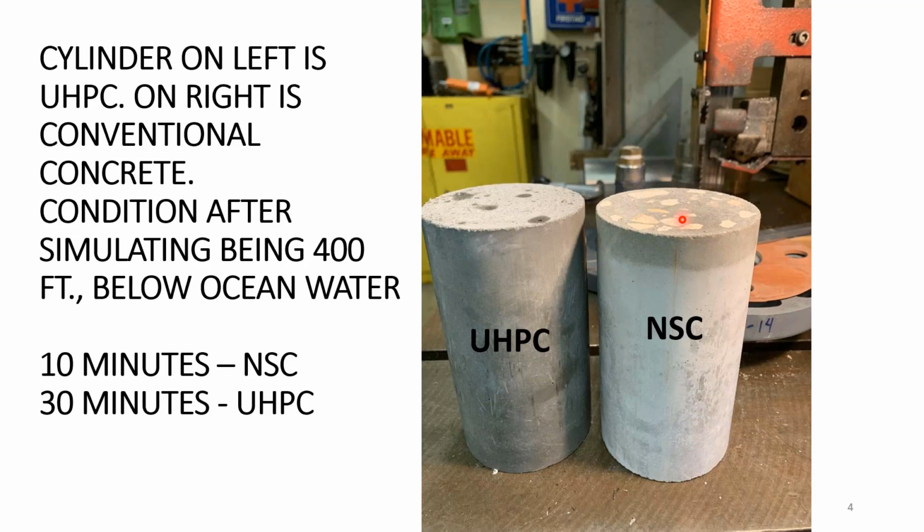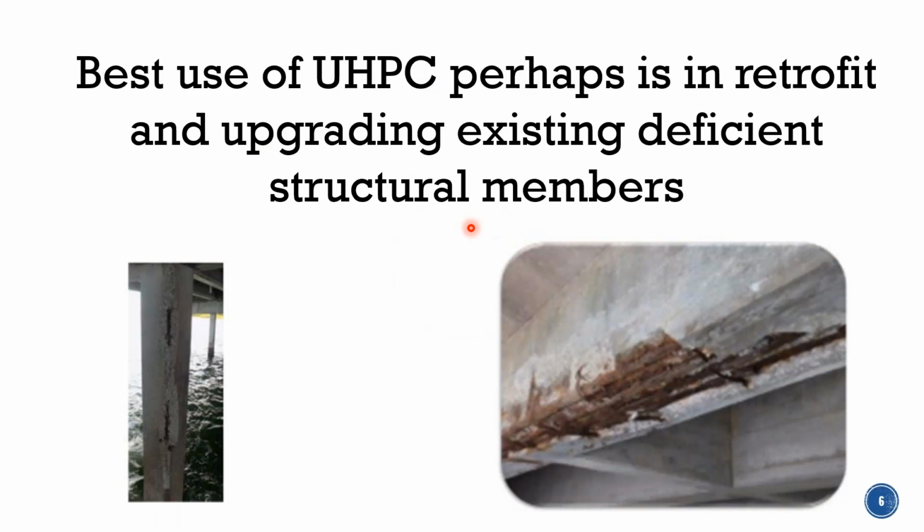On this side, you see a normal strength concrete cylinder, and after 10 minutes, the water ingresses about a couple of inches, at least 1 inch, through the cylinder. The UHPC shows almost none after 30 minutes. Qualitatively, that's just to show you that.